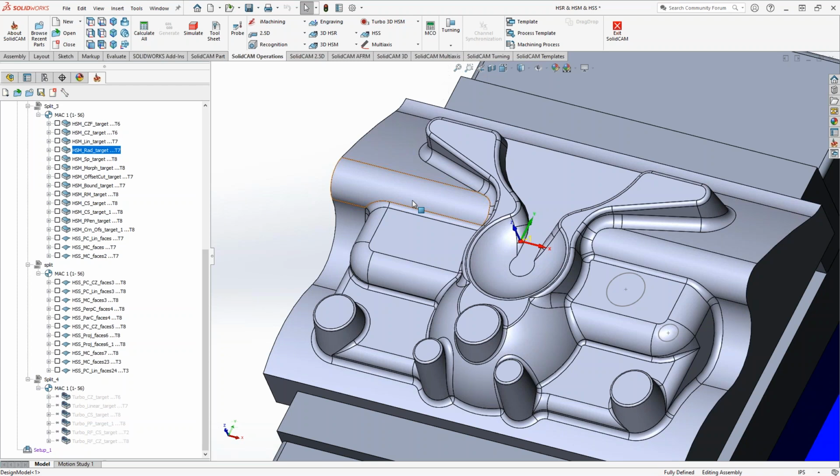But I would say, if you spend less time on programming, there's more time on the machine. If there's less time on the machine, it means that you spend more time programming. You put more detail into your selections, and you're controlling the lead in, lead out, or like we saw at the link section, you're really fine tuning the gap along cut. More time on the programming side sometimes means less cycle time, and this could be one of those things.